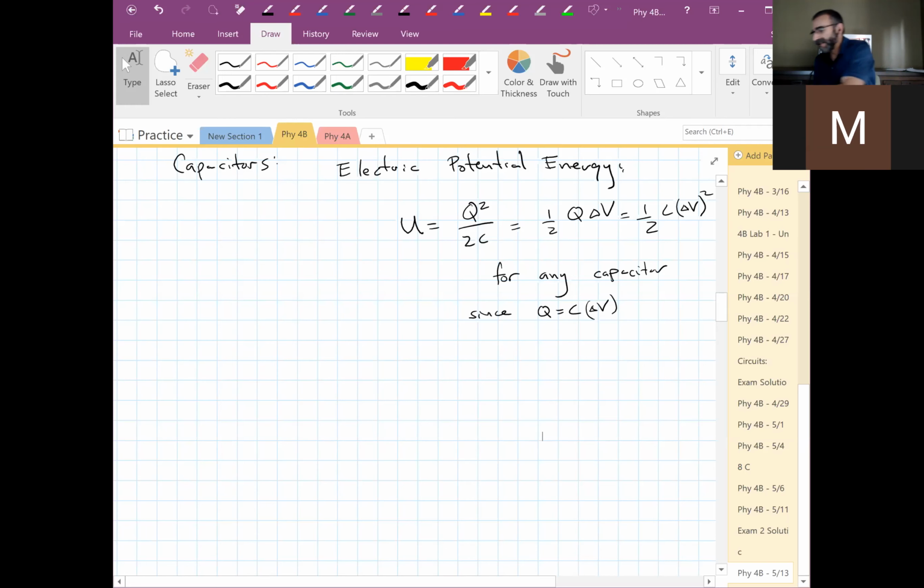And now you have a ton of surface area, right? It's still a parallel plate capacitor, lots of surface area, and a big metal conductor, in a relatively small package because you can manufacture it that way. Roll it up, stick in a little cylindrical pouch, and now you have a little capacitor you can plug into your circuit board.